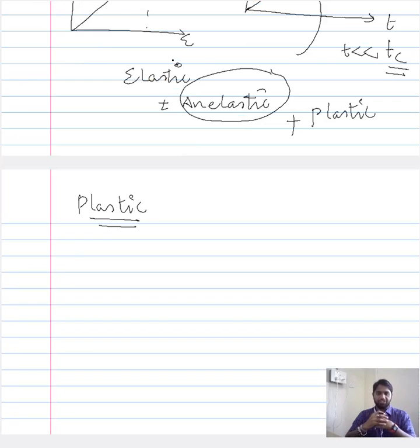Once you start to have dislocations, with increase in the plastic deformation, the number of dislocations proportionately increases, meaning the dislocation density also increases. With increase in the dislocation density, the migration, the gliding or the propagation of the dislocation that translates into the plastic deformation will be confined.